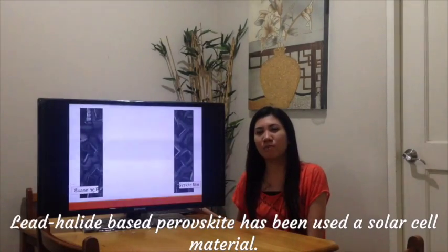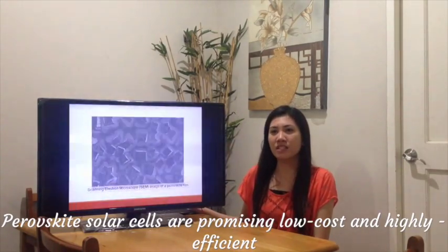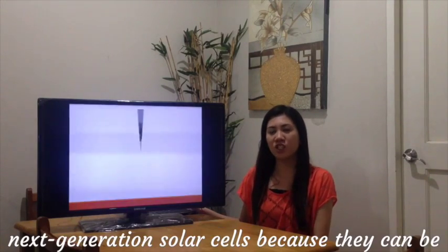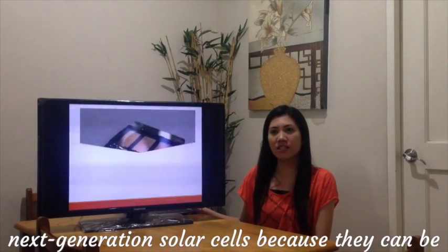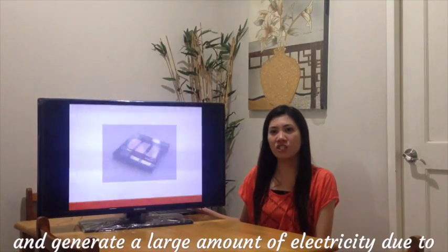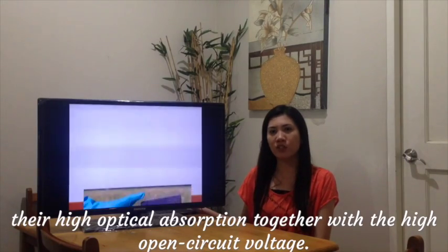Lead halide-based perovskite has been used as solar cell material. Perovskite solar cells are promising, low-cost, and highly efficient next-generation solar cells because they can be made through a low-temperature process such as spin coating and generate a large amount of electricity due to high optical absorption together with the high open circuit voltage.